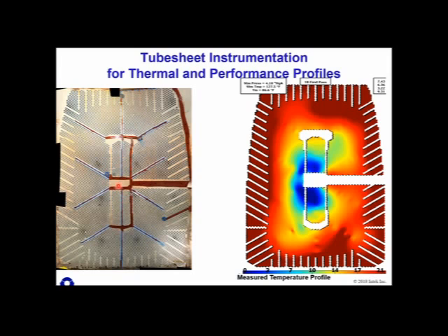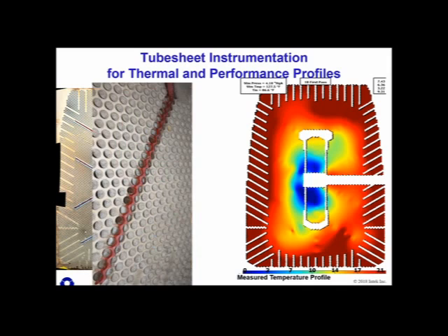So we install hundreds of temperature sensors. We use an instrument called a high density temperature array. The high density temperature array, unlike the device that I showed you in the performance test code, that's a single point measurement, and you have to run one wire for every one measurement. It's a real pain. We've done it before, but we've moved off of that.